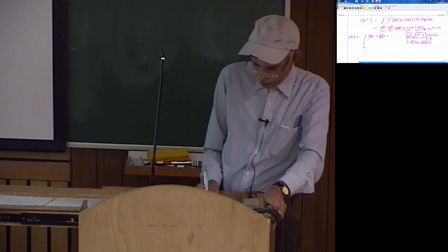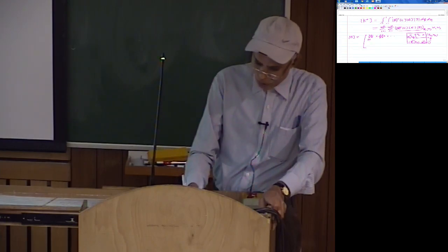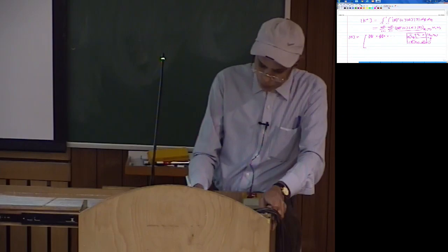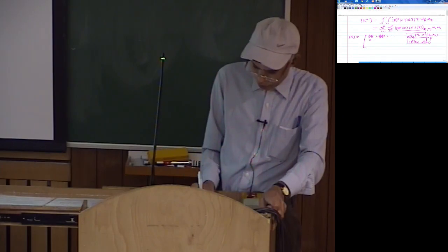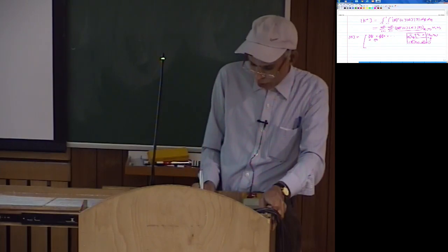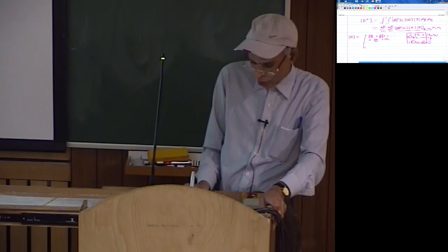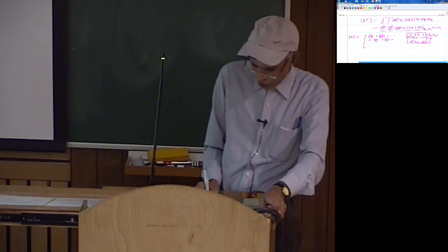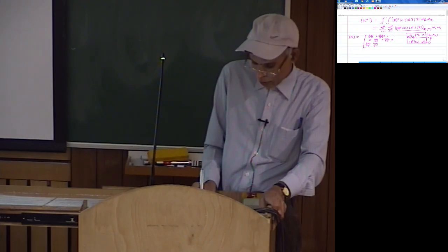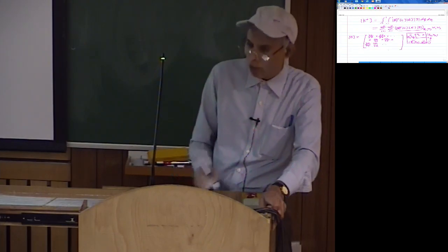So then you have the terms here, sorry, this is 0. Say if it was a plane stress, plane strain problem, so you have del n1 by del y 0, del n2 by del y 0, and so on, and here del n1 by del y, del n1 by del x, and so on. So you have to evaluate this.